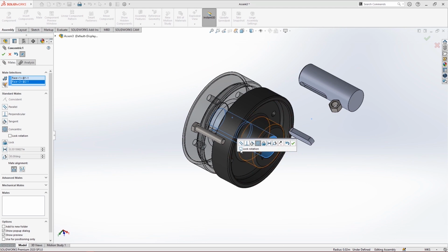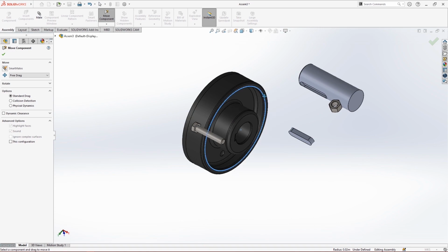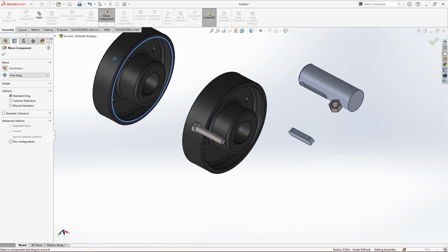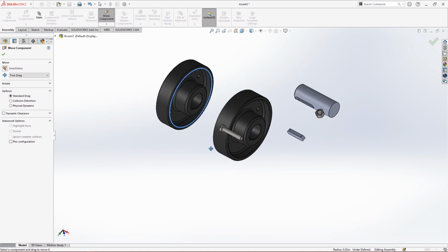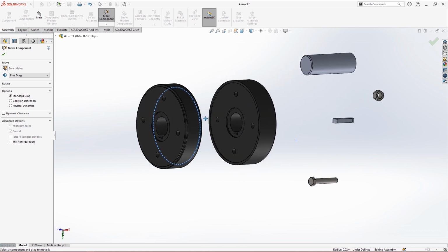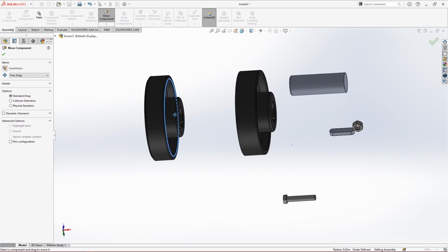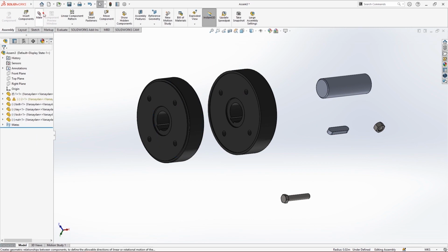You can also lock the rotation, otherwise just click out of it. Now when you go to move here, it will always stay in this axis. It can rotate, and it can even move along, but their axis of center will remain the same. So this is what is happening. Now they are both connected in a way that this side has to touch the other side. The planar sides are touching each other. We can achieve it easily by using a mate.